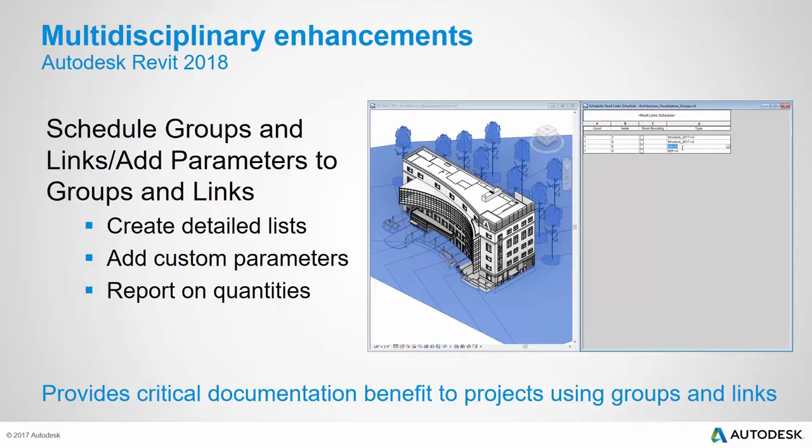What a lot of us have done is we've taken either an area and leveraged areas, which is extra work, or we've taken the walls that surround those units and we've told them that they don't bound rooms, so we have one big room that floods, but then you can't get unit by unit rooms, and it's kind of annoying. Well, with these groups here, you can actually schedule them now. And you have the ability to add parameters to groups if you want as well.